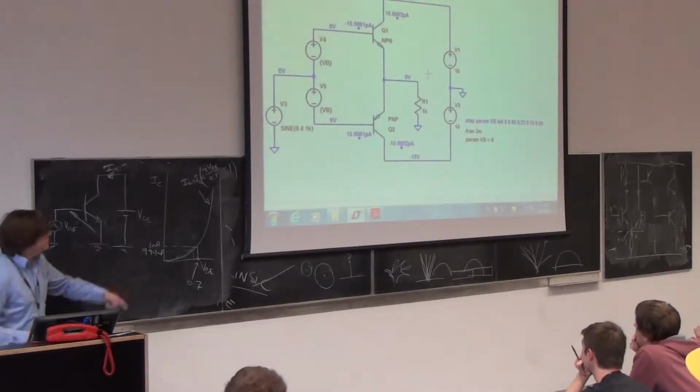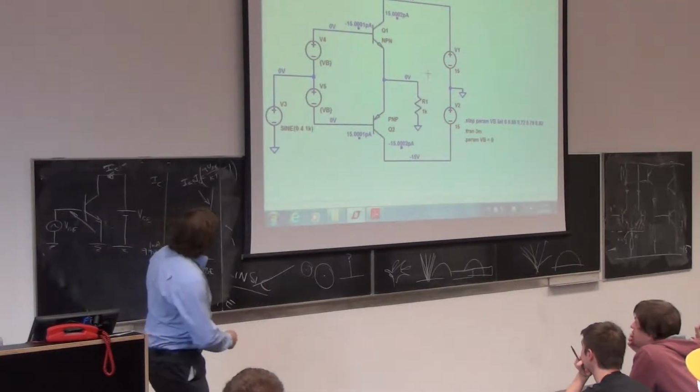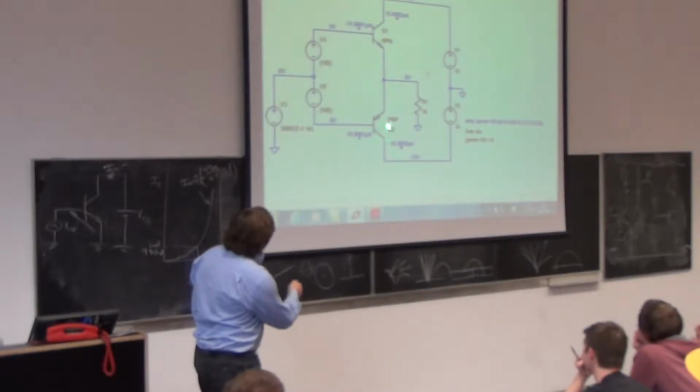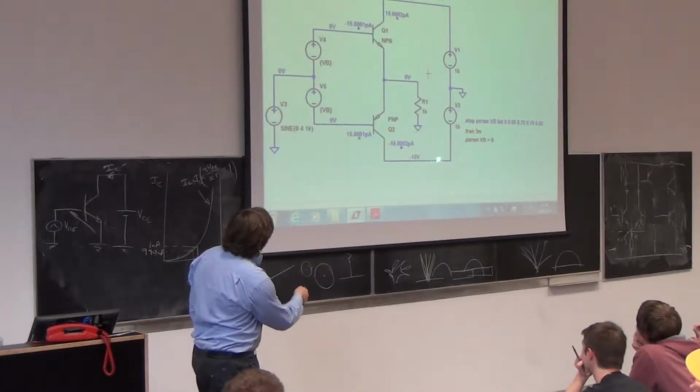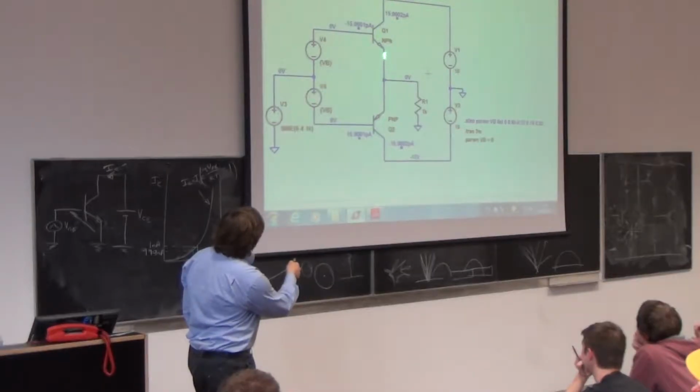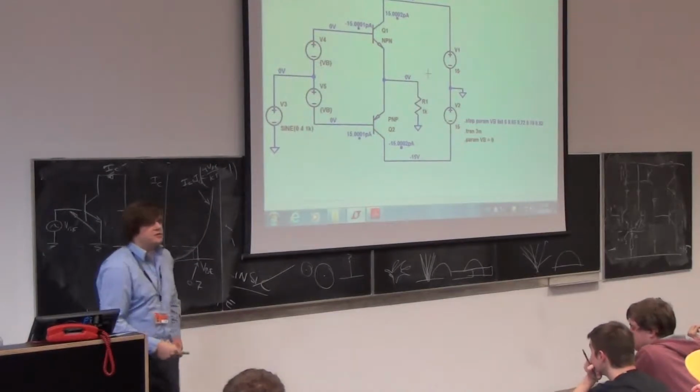So this is a push-pull stage. We'll look at it in a bit. If I was a signal here, I can get to ground via that route, going through this transistor and through that power supply, or I can go up here and through there. And if you've been in the amplifier lab, you'll know why that's significant.